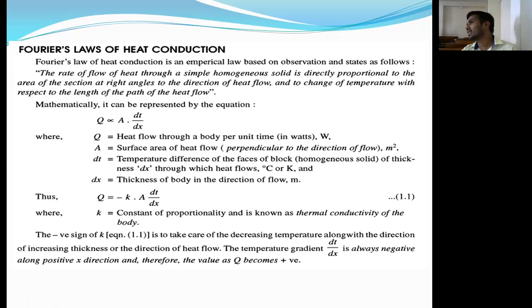So what is the meaning of this negative sign? Whenever the thickness increases, the temperature decreases. That's why the negative sign is there. For solving problems, we have to take the equation as Q is equal to minus K into A into dT by dx.